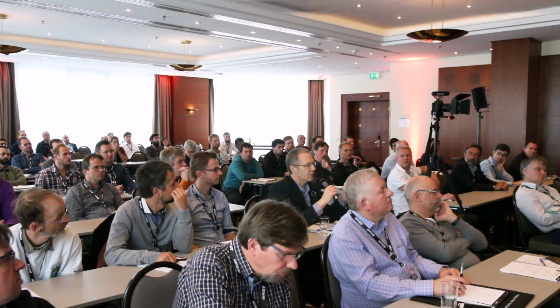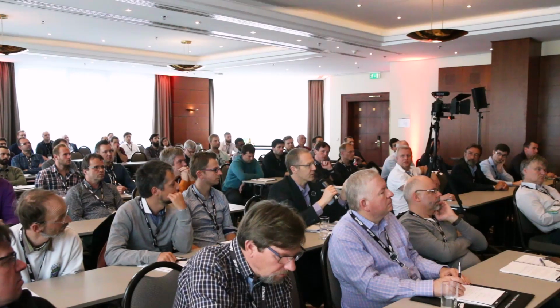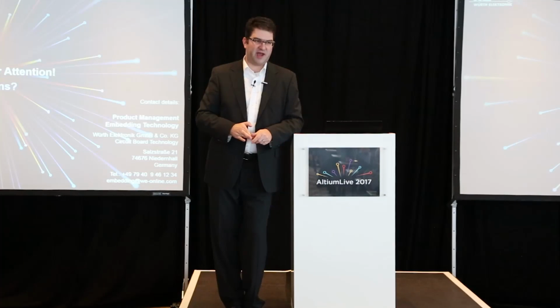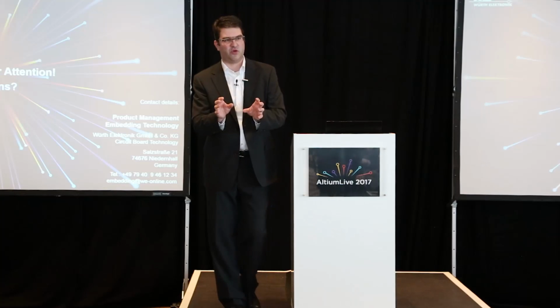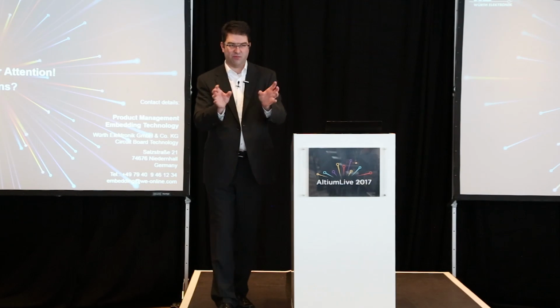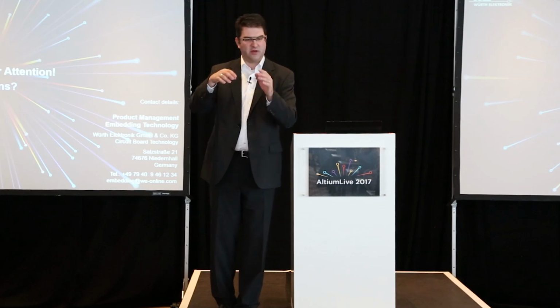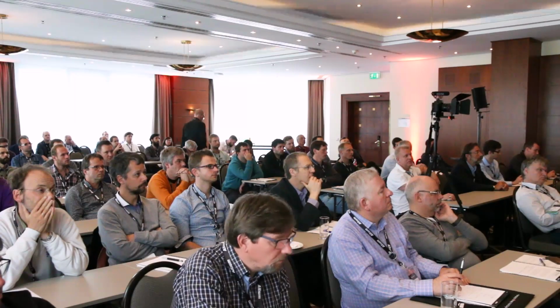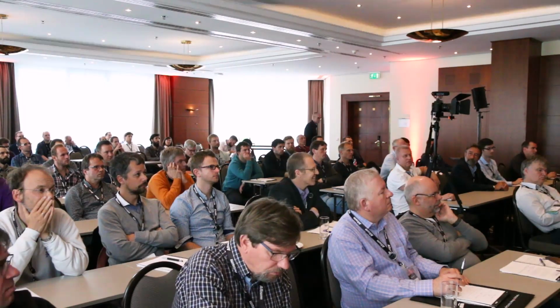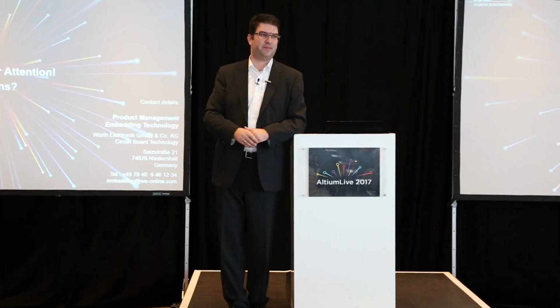And the other question is concerning magnetostriction of ferrite components. Ferrite components, we tried that one, but it's really critical. Ferrites are very brittle, so normally they tend to break when you try to embed them. There is a workaround, and we have several products running with it, where we create a cavity inside the board so that they are not attached inside. They can move around inside, with tolerances and everything, so that they can move 100 microns. But that's not what you really want to do. Ferrites are really critical in that case, especially when they get bigger and bigger.